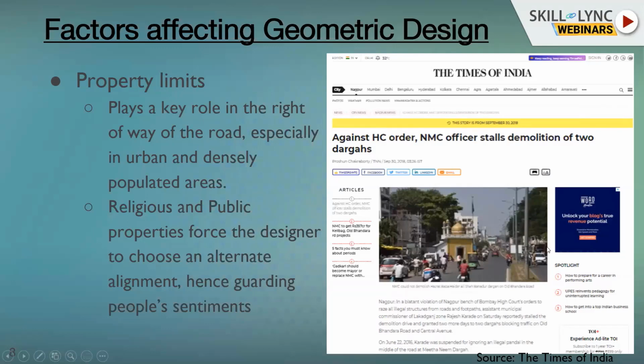If you just move this center line towards the right side, then all the geometry after that and before that will get disturbed. So a lot of property acquisition would have to take place. In an urban situation, I don't think that could be possible. So that is why some people might have simply constructed this road, even though it is a technical failure in terms of geometric design, because they might not be able to help it because of the government and other issues.